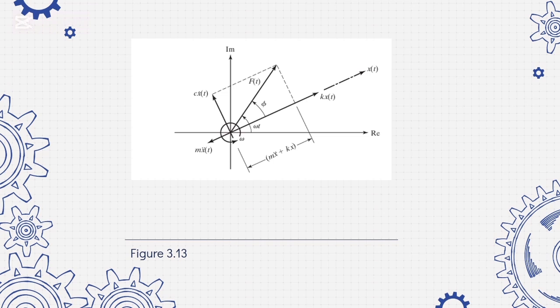The damping force leads by 90 degrees, and the spring force aligns with the displacement. The third vector balances the external force projected onto the real axis for physical interpretation. The diagram clarifies phase relationships and dynamic force balance, aiding engineers in tuning systems to avoid resonance or excessive vibrations.